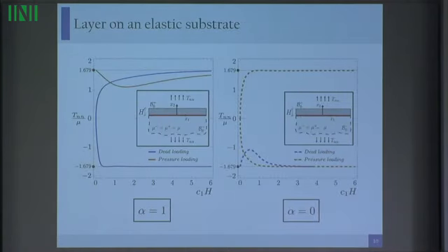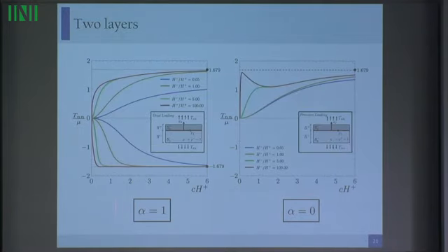This remains more or less the same if we analyze more complicated problems. For instance, we have a layer on a half space and they are separated by this sliding interface, and we have now a tensile orthogonal stress. And again we see that with the correct condition the bifurcation diagram is completely different. Again, if we consider two layers, pulled in tension with a slipping interface, the correct condition and the mistaken condition give completely different answers.